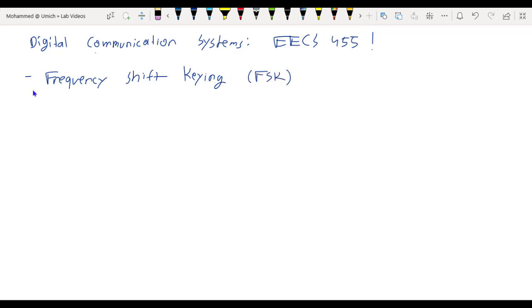In binary FSK, the data is transmitted as a sequence of tones or sinusoids, where each tone can have only one of two possible frequencies. The higher frequency tone will be assigned the binary digit 1, and the lower frequency tone will be assigned the binary digit 0. And so the audio file provided to you on Canvas has a message encoded in it, where that message is a base 10 number between 0 and 255. And this number has been converted into its corresponding 8-bit binary string. The computer will then transmit this 8-bit binary string using a sequence of 8 binary FSK sinusoids, each of 2-second duration.